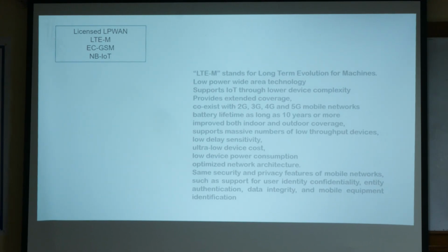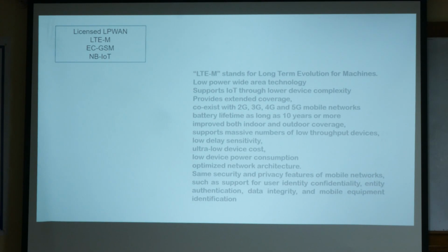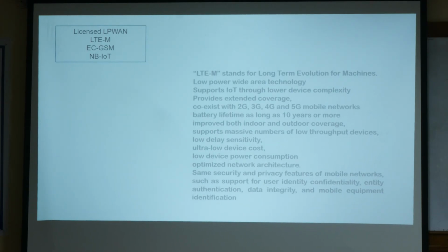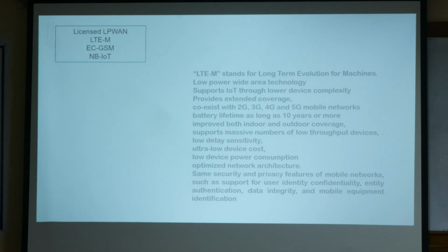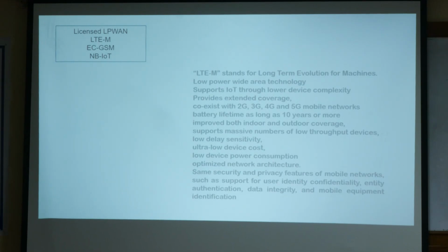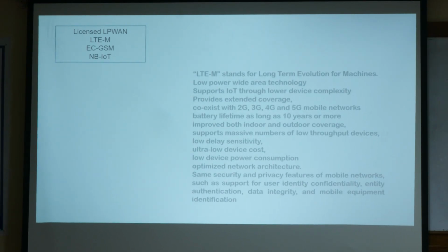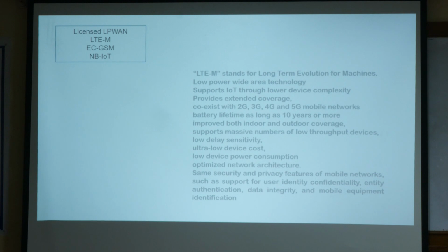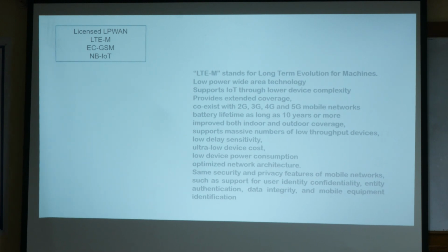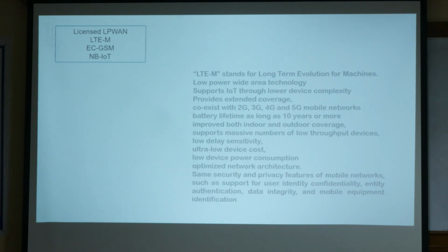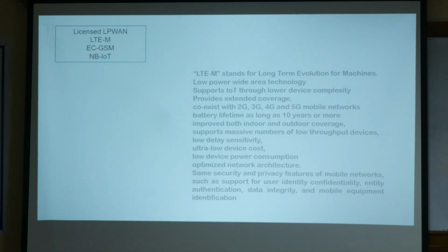So why do we have to do that? Because for the base station, the user might be near or far away, so both cannot be given the same power. One user has to be given minimum power, and for the other the power has to increase. So we need some type of learning algorithm to find how far it is, and adjust our power until sufficient. Sufficient means your receiver has a sensitivity, and the received signal should be more than that sensitivity value. So we go stepwise and do it. So they are good algorithms.